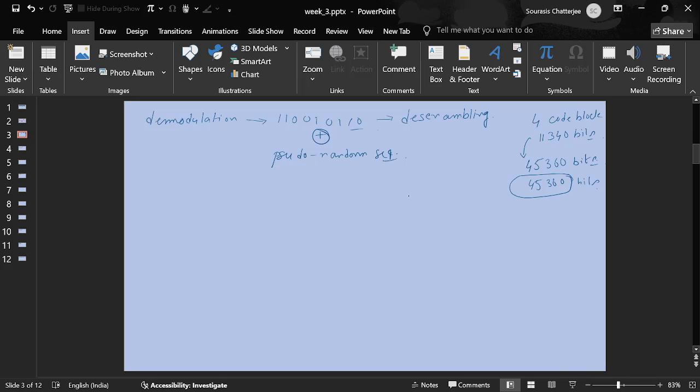Implementation becomes difficult. Yeah, because you will have huge memory overhead, and this is also not a single pseudo random sequence, right? For different users, for different tasks, you very well need to use a different pseudo random sequence, and your payload size is constantly changing. So how do you exactly mitigate this issue then? Is there any particular name that is used in the 5G NR framework when it comes to the implementation of scrambling or descrambling?